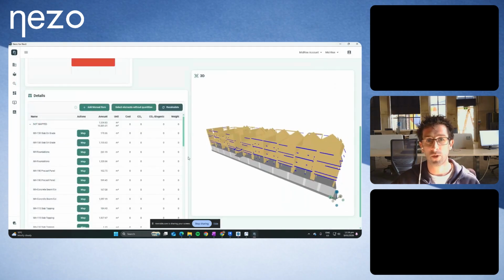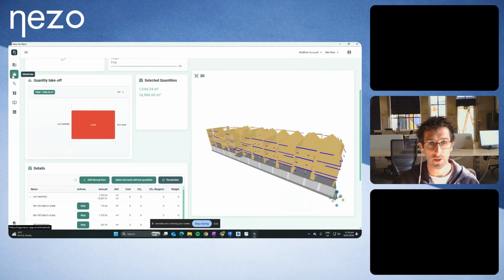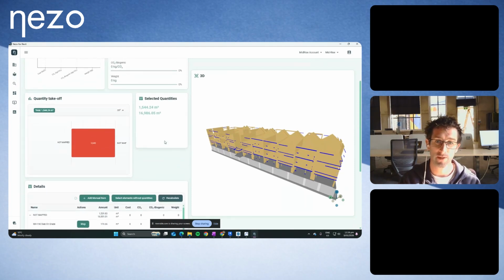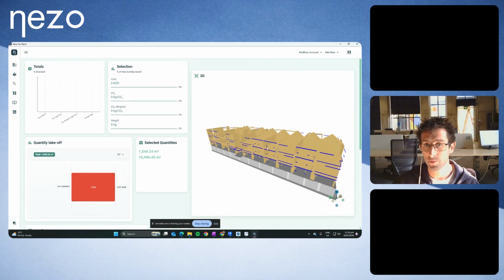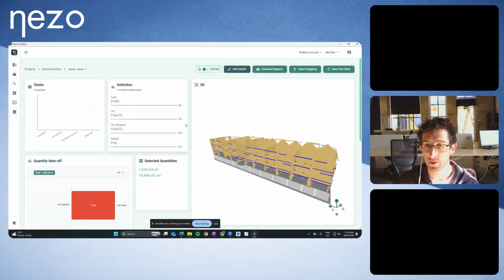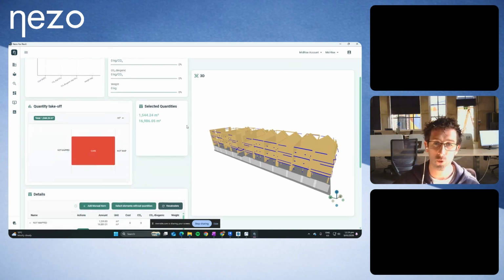Cool. So what I can do is go to the material library and import materials into the Revit file and place them on the model itself. So that's one pathway of linking data to your design. That's actually useful in the MidRise tool because you have only one project space. It's a good way to save your project. You can actually save the Nezo and MidRise assembly materials directly in your model. Whenever you click sync and the model pops up on screen, you'll instantly get carbon, cost, weight, sequestered carbon, data feedback. And there's no additional mapping step.